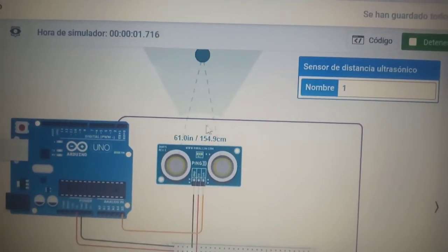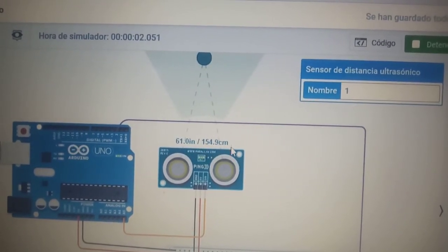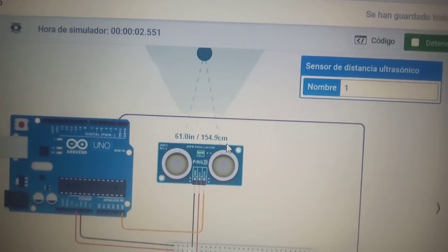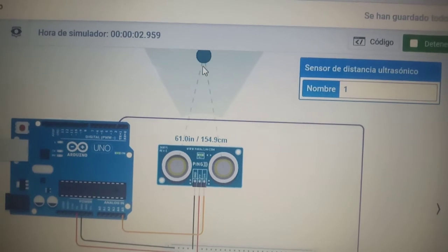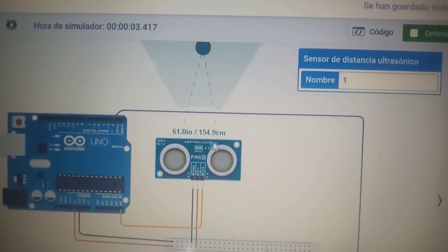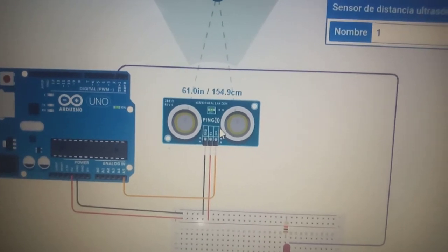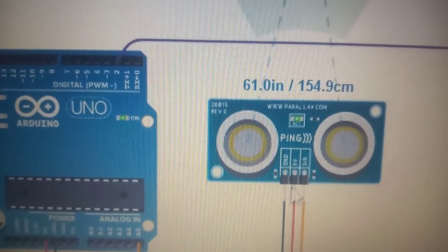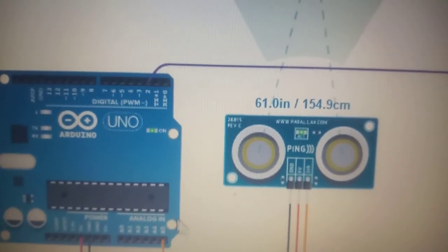And then the unit that we programmed in the block diagram is going to be related to the value right here, depending on the units that we have selected in the instruction for the ultrasonic sensor, whether inches or centimeters. We are going to be playing with this little indicator, varying the signal. And as you may have already consulted in yesterday's activity, this is going to be negative, positive, and this is going to be your input for the analog inputs of the Arduino board.